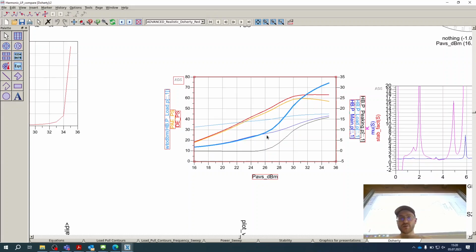but the efficiency is not only 60% for the peak application. Normally, how a normal transistor or power amplifier would behave is that the efficiency peaks at the maximum input drive and then goes down linearly to very low levels. But what this device does is that it retains a high efficiency, over 60%, across a wider range of operating input drives. For example, from 35 dBm input to 28 dBm input, you have above 50% efficiency. This is just the property of the Doherty. It doesn't mean anything more. It's just a type of amplifier.